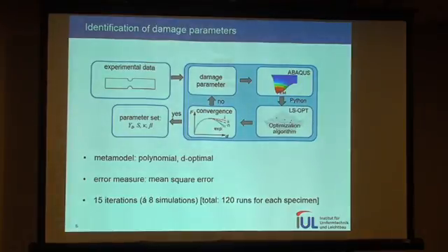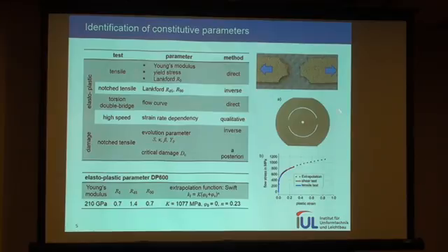How have we identified the damage parameters? We have used the notch tensile test with an initial guess of the damage parameters, and simulated the notch tensile test in 3D, using of course some anisotropy planes. This is a valid approach because, as you can see here, and what I have not pictured here, the crack is perpendicular to all three directions.